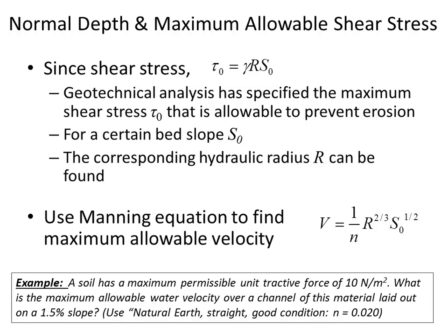What will increase the velocity of a channel, for one thing, is if it's got a very steep slope. And if any of you have been skiing before, you know the way to reduce the slope, if you're going down a hill, is to meander back and forth. And so a meandering stream increases the length, because now the length of the meandering stream is going to be larger. The delta Z is the same between point 1 and point 2, but effectively you can reduce the slope by increasing the channel length.